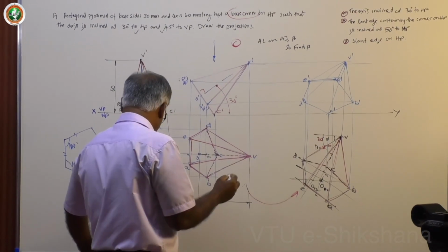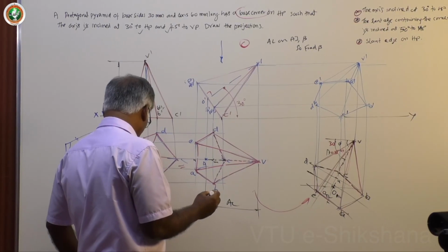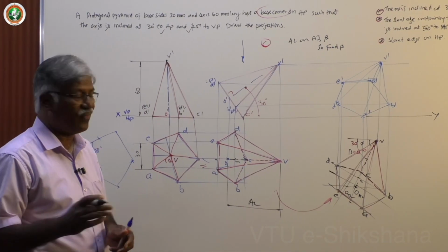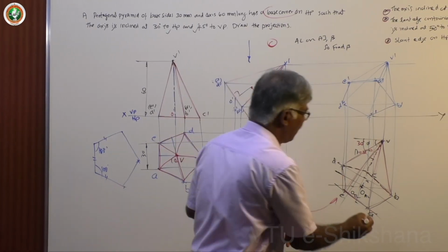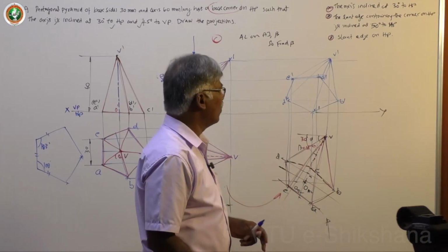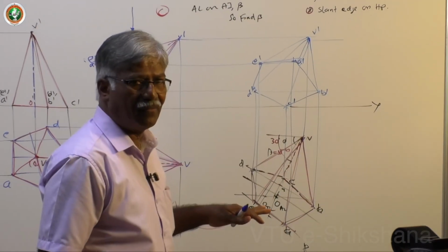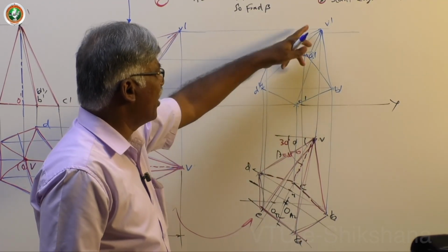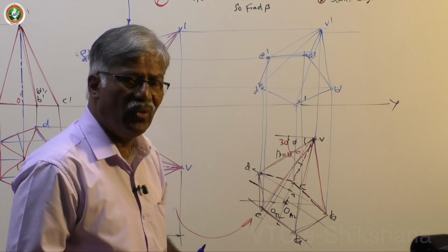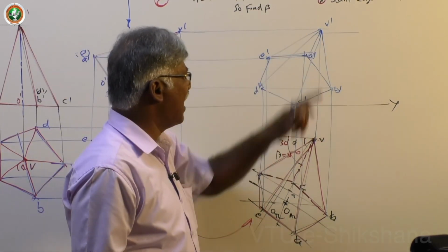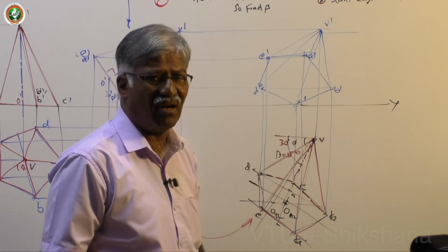This again refers to the key surface reference or the farthest straight line. Let me take the farthest point only and check. See, V is the farthest point from you, V is not visible, fine. Normally we say all edges which are joining V are not visible, then there will always be confusion. Say okay, E dash V dash and B dash V dash are not visible.